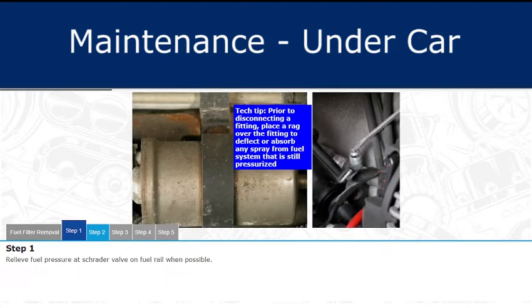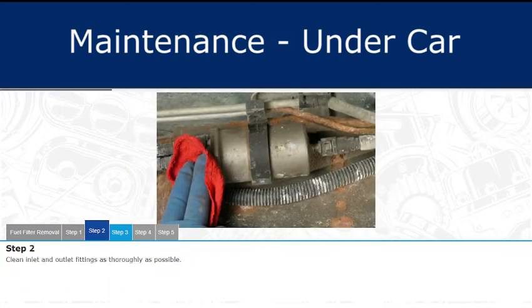When possible, relieve the pressure in the fuel system at the Schrader valve on the fuel rail. Prior to disconnecting a fitting, place a rag over the fitting to deflect or absorb any spray from the pressurized fuel system. Thoroughly clean the inlet and outlet fittings.